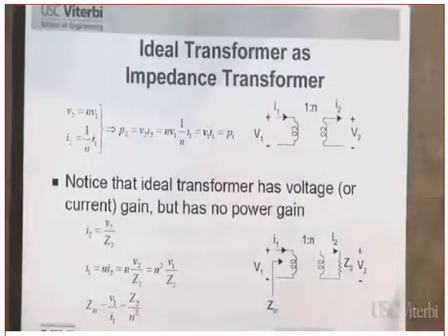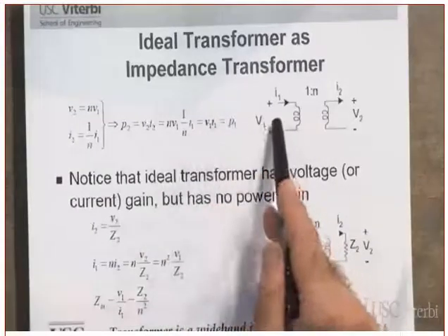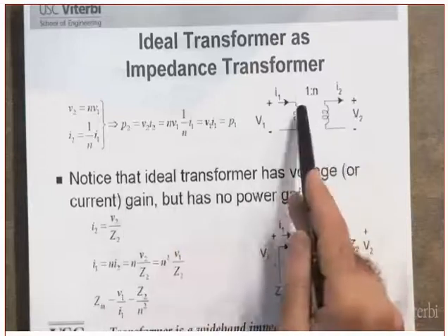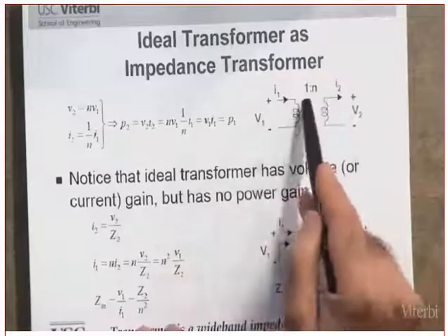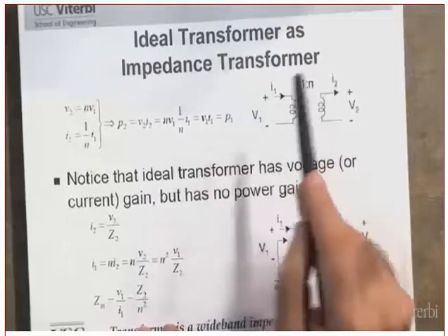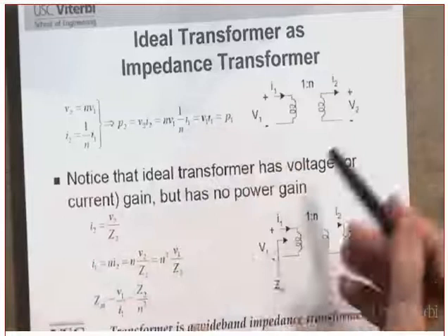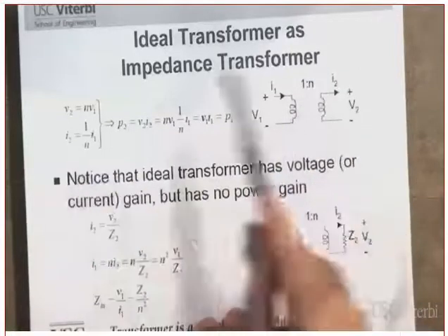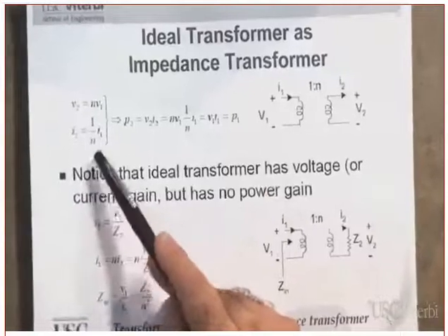The first one, of course, is a transformer. Now, we call it an ideal transformer, in the sense that the input power is the same as the output power. Now, we saw the relationship, if this is 1 to n. By the way, in the exam, if there's a problem with this, be careful and look at this carefully, whether it's n to 1 or 1 to n. So, don't rush right away, use the equations. Be careful about that. In this case, it's 1 to n, which means V2 is equal to nV1, and I2 will be the other way around, 1 over n, I1.